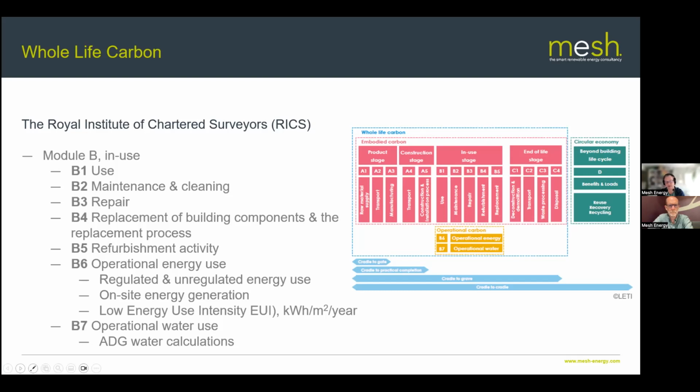And for us as building services engineers, it's important to understand the replacement life cycle of solar panels because building services plant can vary in its life cycle between 15 and 25 years. So it means that some elements of the energy strategy, as it were, might be replaced 3 or 4 times during a 60-year lifespan of a building.